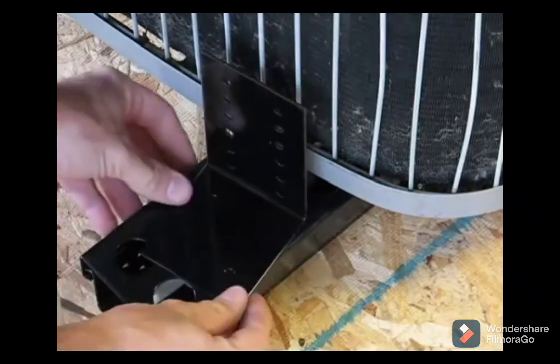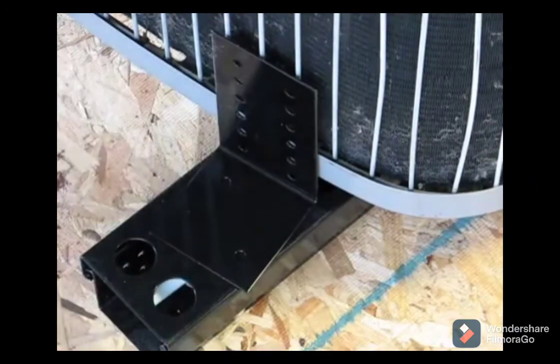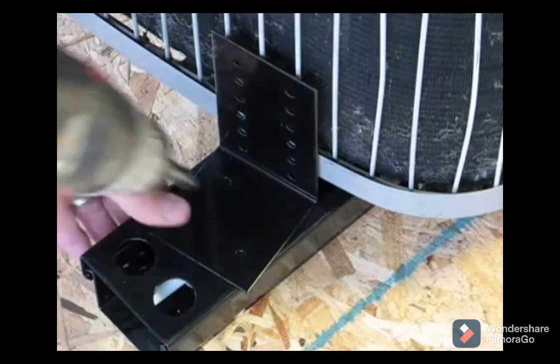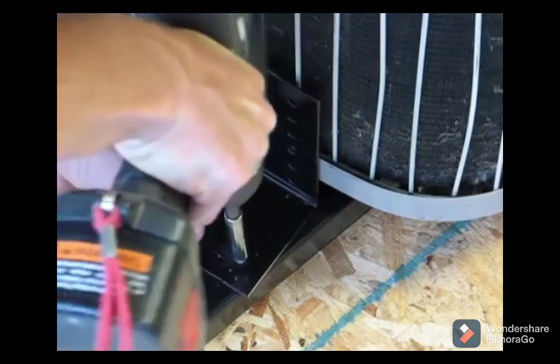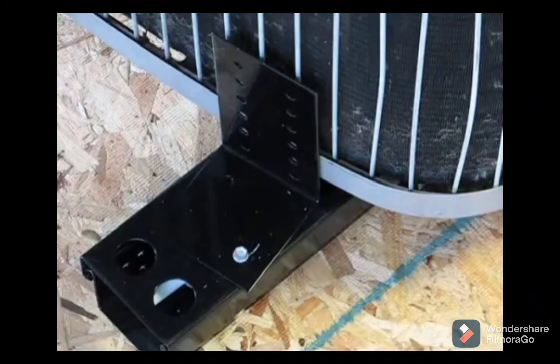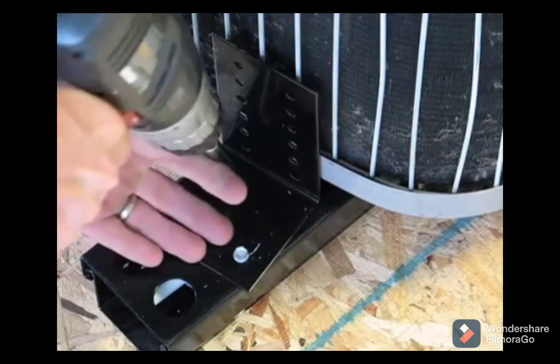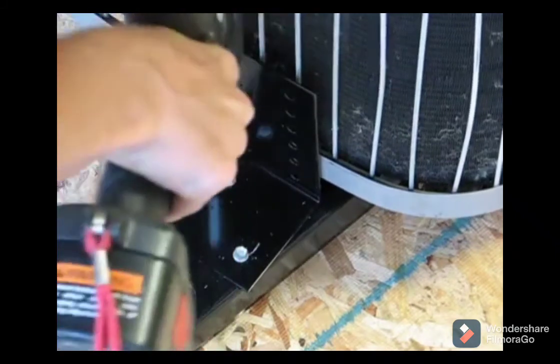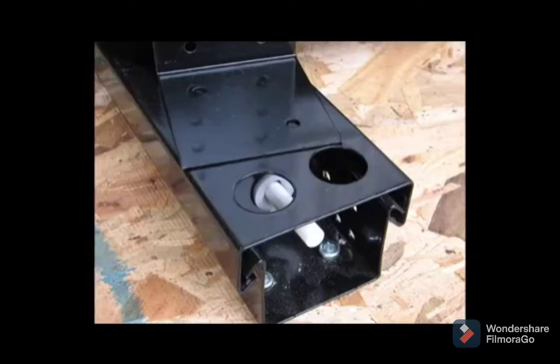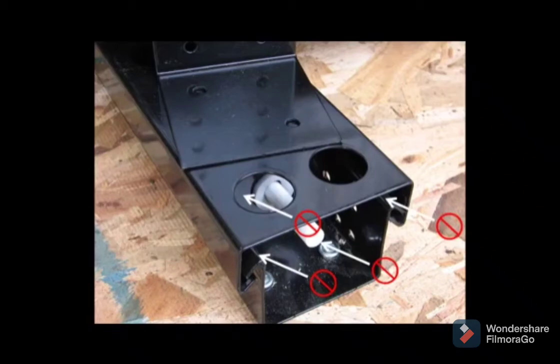After the condenser has been properly located upon the isolators, attach the 4 supplied brackets to the top of the isolators using the included self-tapping screws. Position the brackets such that the face of the bracket is flush with the mounting surface of the condenser, and drive 2 self-tapping screws per bracket into the isolator to secure. Ensure that the newly driven screws do not interfere with any of the internal components, including the bottom of the isolator. Screw locations other than those provided may be used if interference is observed.